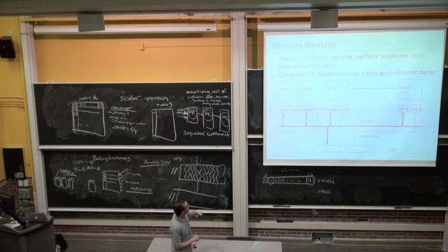So basically, you don't have a problem if your stride is relatively prime with the number of banks. Then your consecutive accesses go to different locations. But if your stride is a multiple of the number of your banks, then you have a lot of bank conflicts. If you're not relatively prime, if you will. So another way of doing this is actually having a prime number of banks.